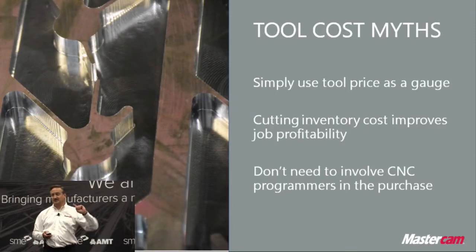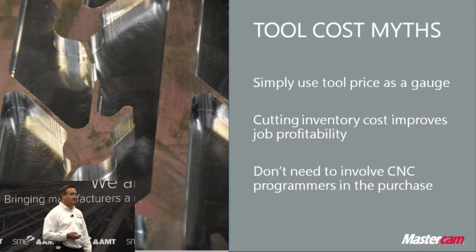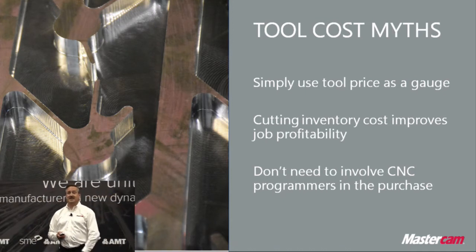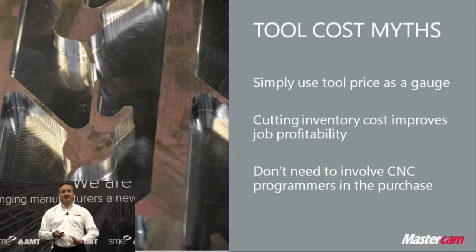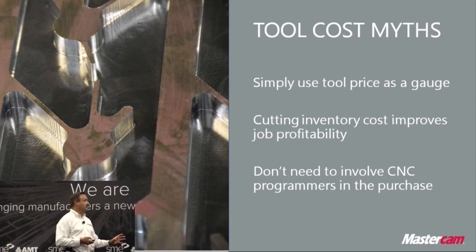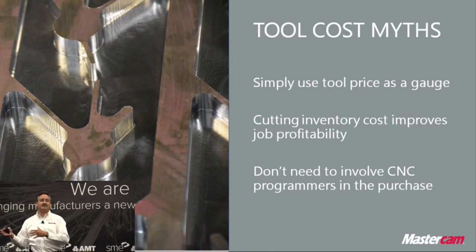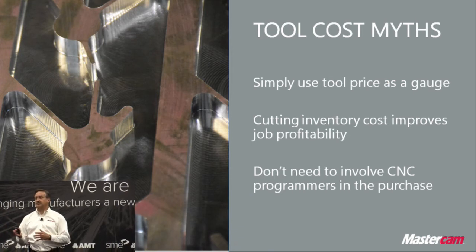So, going back to our tool cost myths. Okay? If you're using price as a gauge, that's gone. It's no longer about just simply price. You have to factor in material removal rate and overall tool life, and even massage your cut parameters so that you're maximizing both as much as possible.